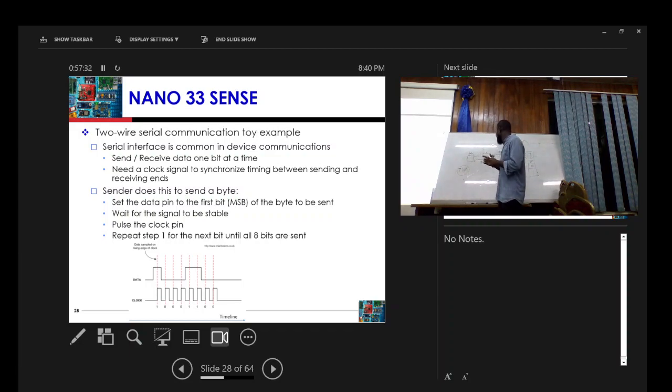Do you understand? So I said one wire is the clock, and one wire is the data, right? If I want to send data, I have to activate the clock, and then I send the data through the data wire. Let's say I have this Arduino board here, one, and Arduino board here, two. I want to send 1010, this number.